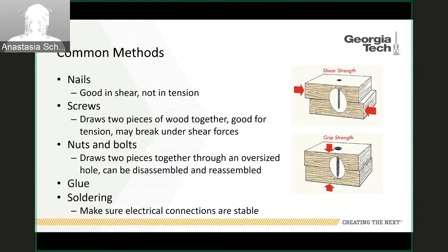Nails are great in shear. If you have two pieces of wood that are going to be pushed against each other in shear or slid against each other, the nail will be great for keeping them together. But if you're trying to pull those two pieces of wood apart, the nail really isn't going to do anything for you because it has no hold on the material. It's not biting into anything.